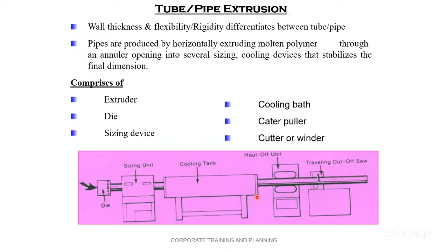But friend, for a final product, you require a specific size, length of this cooling tank. There's no such effect on the granules, because granules we have to cut very immediately. For example, nylon, and that's why we are keeping it in a very hot condition. It should be cut immediately.